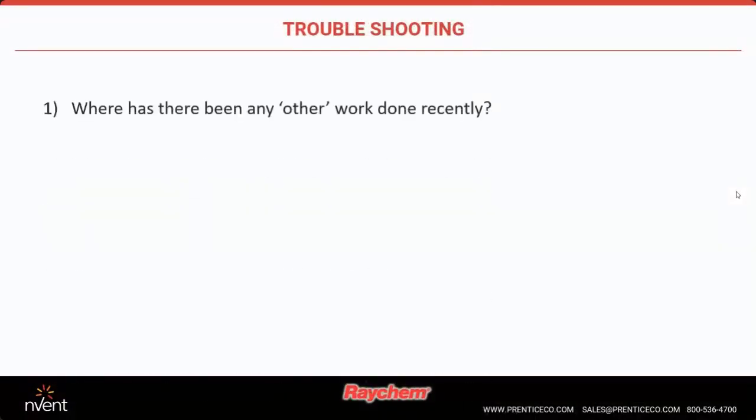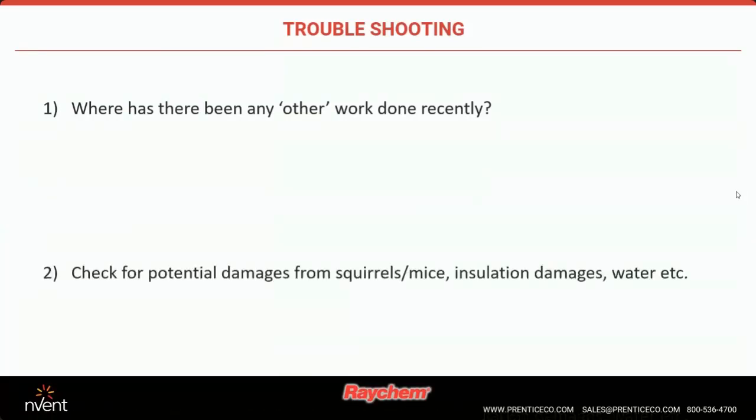All right, let's get into some troubleshooting. Troubleshooting, I find oftentimes if you have a system that is working fine, it's been working, no problems with it, and then all of a sudden one day out of the blue, it's either blowing a breaker or tripping because of a ground fault, I highly suggest looking at this job site as a whole, looking at what other work is being done in the area. In a lot of cases, that's going to get you directly to potentially where that problem is.